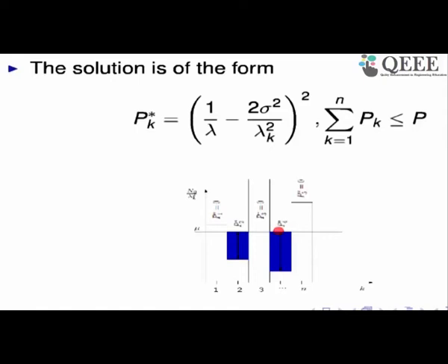So this is the second important point for the case when the channel state information is available at the transmitter. From a capacity perspective, it doesn't give you much gain by coding across different modes. First thing. Second thing, each mode contributes a different level, so you need to do power allocation. Uniform power allocation is not suitable. The power allocation follows a water filling algorithm. That's why, for the case when the channel is known at the transmitter, you need to do water filling.